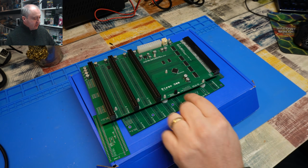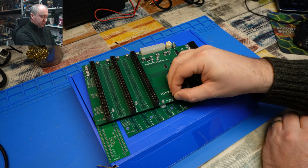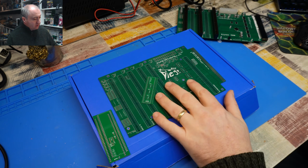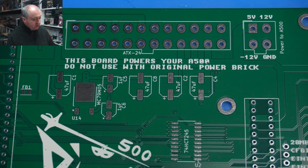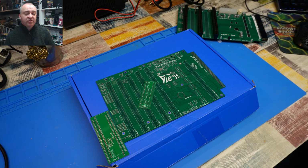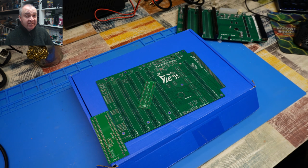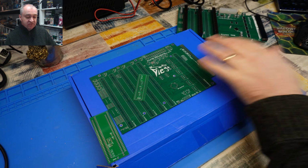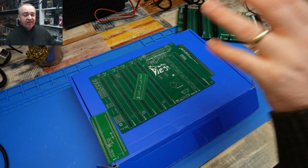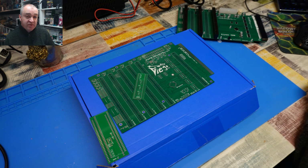There's a switch at that point. Granted, it's just a latching power switch at the minute, but that's what will turn the system on. But that's also why we have this warning on the board here. This board powers your A500. Do not use with original power brick. If you did try to use this in combination with the original power brick, well, the likelihood is that it just won't work. Worst case scenario, smoke will escape from something. If you just try to use this on the side of the A500 with the original power brick and no ATX, it definitely won't work, because we need the 3.3 volts from that to power the CPLD.